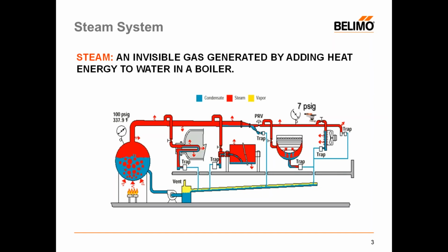On the main steam line there, we see a PRV, a pressure reducing valve. And in my example, which is a little extreme, we go from 100 psi all the way down to 7 psi. In HVAC, it's very commonly used the maximum 15 psi, although some of our HVAC systems may be higher. Generally, we use 7 psi, maximum 15 psi. And by most codes, 15 psi indicates low pressure. Greater than 15 psi will be either medium or high pressure. And then you can get into licensing and whatnot, how that changes.